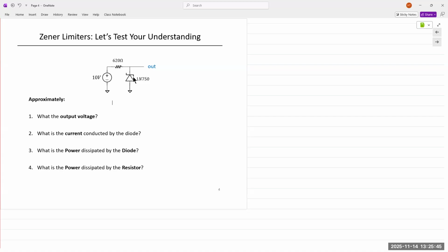So in terms of operation, if you want to just look at it as an off-the-shelf component, there is no difference. Forward bias diode requires 0.7 volts to turn on. Reverse bias Zener diode requires a certain amount of voltage to turn on. That's the way we should look at the circuit.